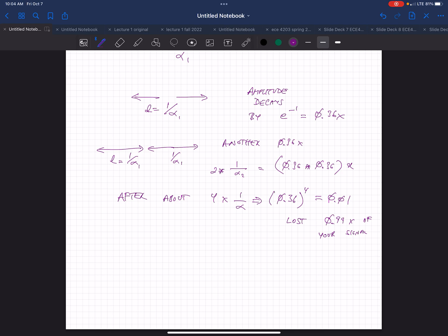If you're on a silicon chip, because the substrate is silicon, which is a semiconductor, your losses are big and your lines are thin. So if you're just running millimeters and at high speed, you run into trouble. So it really depends on the frequency you're in and what business you're working in.